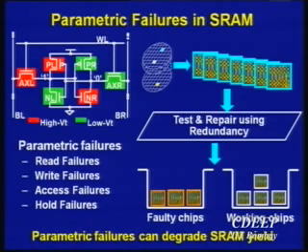And what I'd like to ensure is that that doesn't go beyond the trip point of the inverter on the left side, right? And if it does, then there's a possibility of failure, right? So now, let's look at a worst case scenario where my access transistor on the right side has a low VT, meaning higher strength, right? And my NR, which is the NMOS transistor on the right side, is of high VT.